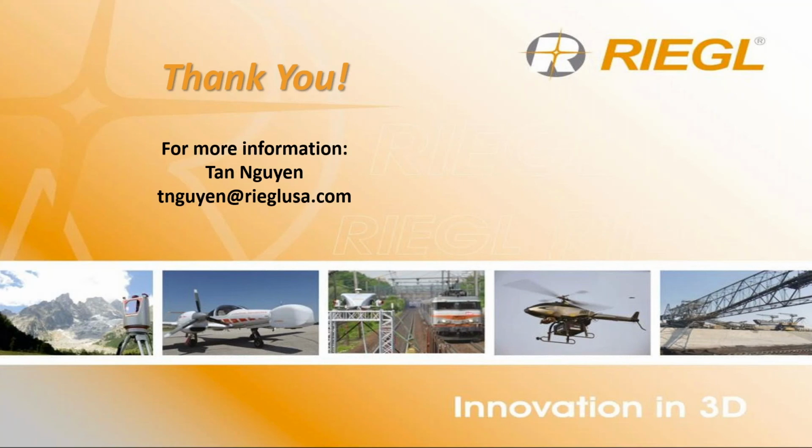So, and I've seen this from a lot of universities. A university, they don't have the budget to buy these high-end differential GPS. They use like a handheld. Well, you can make use of it, but it's going to be a little bit more work. And what I mean about a little bit more work is you lose the accuracy of the position of the GPS to where the scanner is, right? Because you don't have it fixed mounted. I don't know how you guys are mounting it, but if you're just like setting your hand over it, yeah, now you're guessing where that GPS is supposed to go.